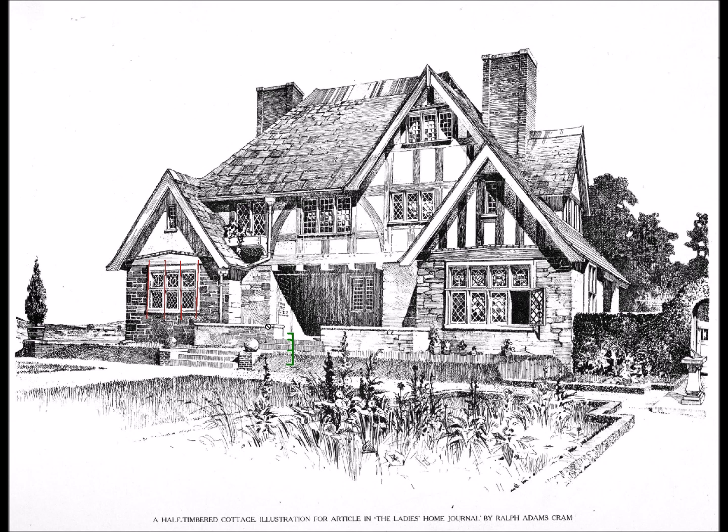And here, the opening for the porch looks like it's 4 chunks wide, 4 units wide. We've got a window up above that would be, if these windows are 2 feet wide, about 6 feet wide, and these beams line up, so that makes this part 6 feet. So 6 feet, another 3, and another 3. That makes the porch about 12 feet wide.